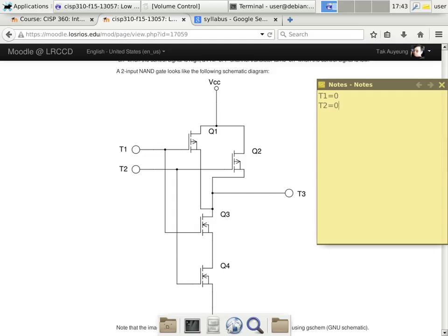So what we do is we follow the circuitry. Okay. These dots mean there is a connection, and without a dot, these wires are just flying over each other. Are there any questions about reading that part of the schematic? Let me just point out using the mouse because this way it's recorded. When you see a dot at the intersection of two lines, it means there is a junction. Electrically speaking, they are connected. When you see a junction where there's not a dot, that means it's just a flyover. These two wires are not connected. So the vertical line and the horizontal line are not connected electrically speaking. Is that okay so far?